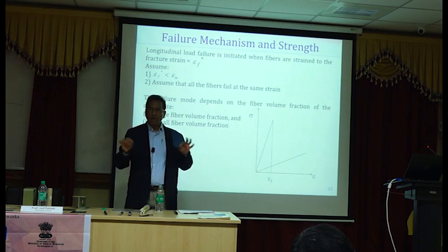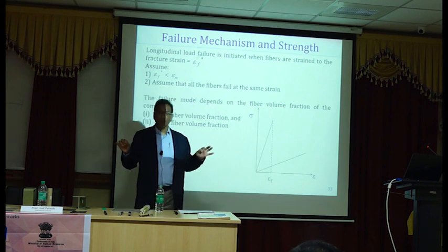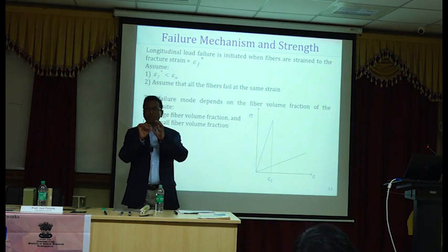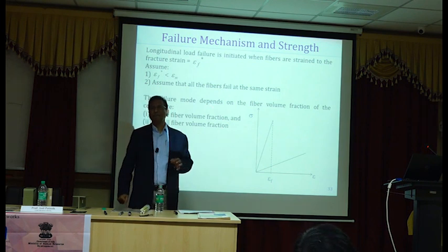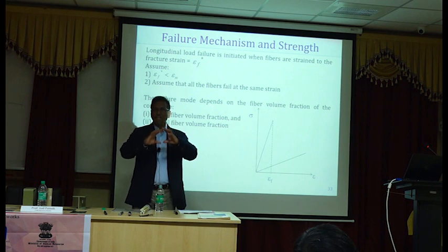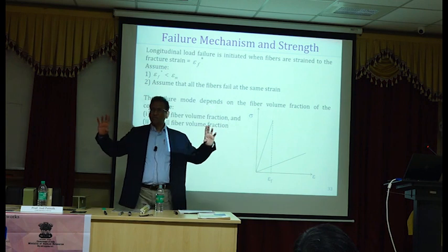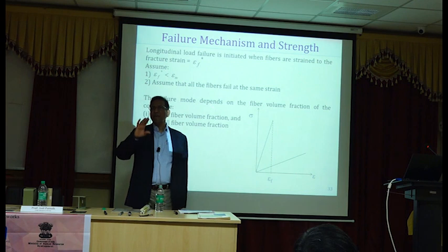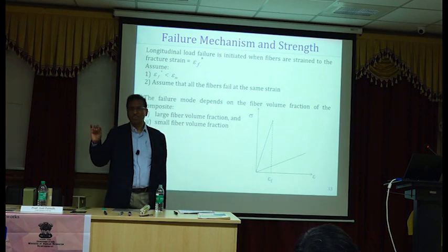If you provide a very small amount of reinforcement, it will become two pieces if the area of steel is less than the minimum. The minimum area is based on the fact that whatever moment strength can be achieved by plain concrete specimens without any reinforcement is the same amount of moment of resistance with reinforcement for a cracked section.